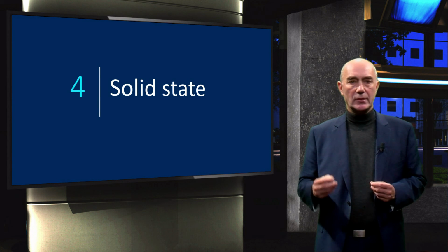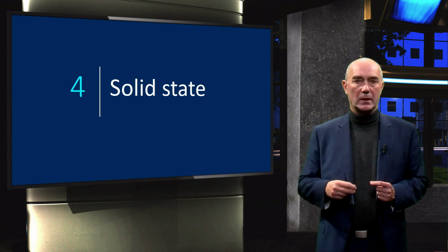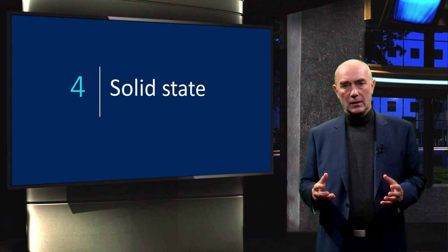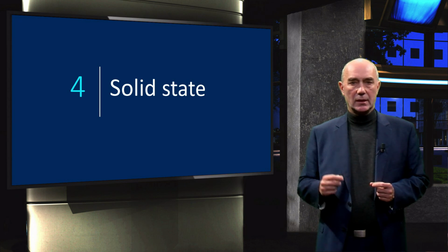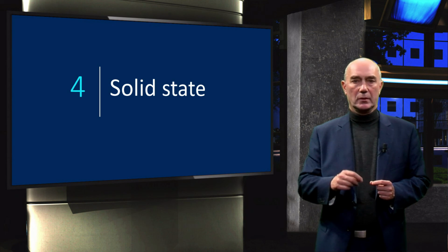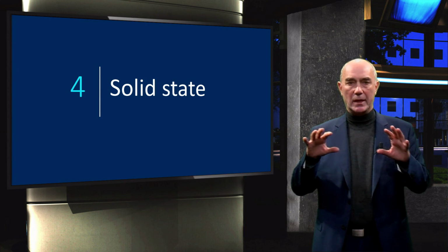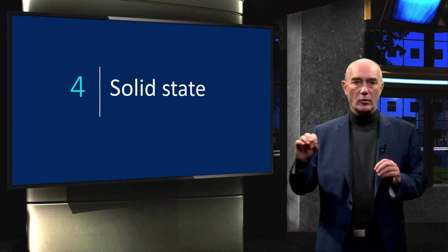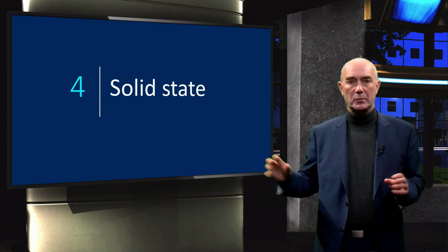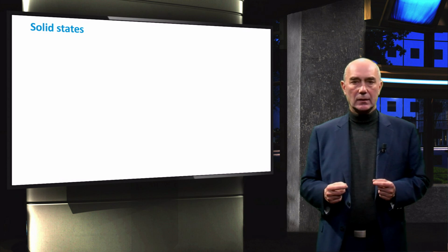Silicon is present in nature as a solid. Silicon is to be found in silica and silicates compound materials. However, for semiconductor applications, silicon has to be mainly in crystalline form and very pure. It means that silicon atoms are arranged in a periodic, regular way with long-range order and without impurities. A solid can be either monocrystalline, polycrystalline, or amorphous.